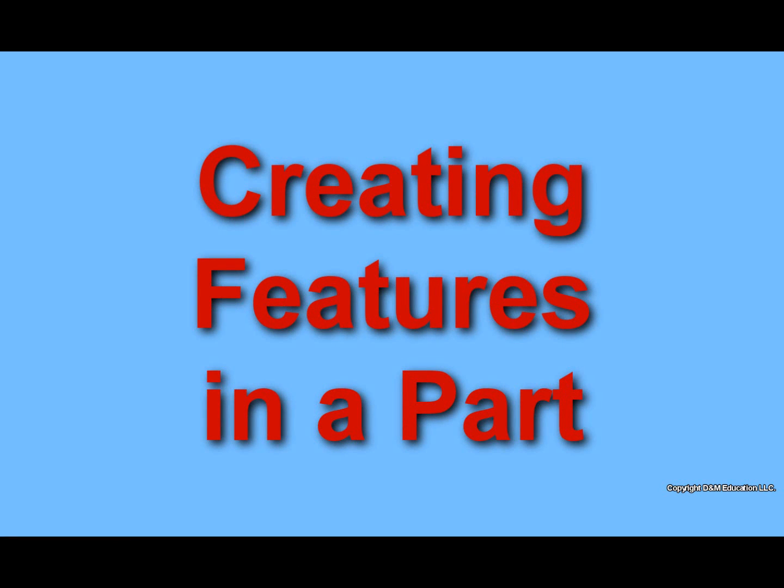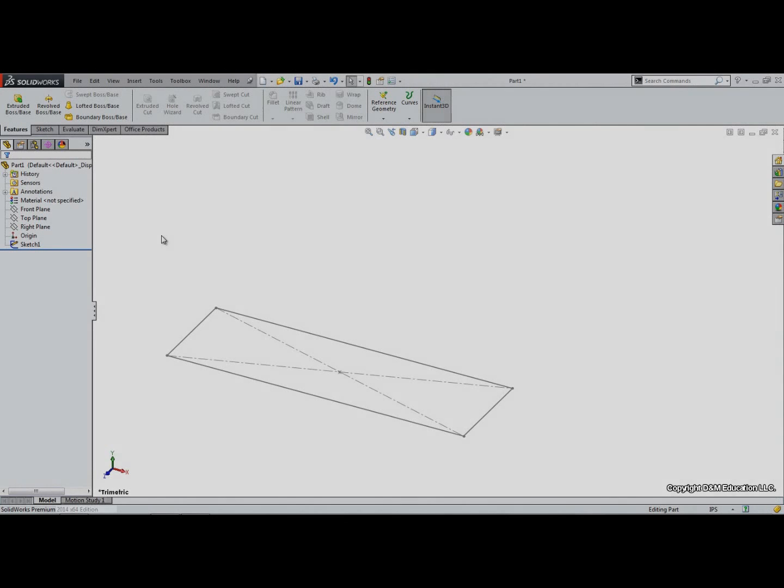In this video, the basics of creating features in a SOLIDWORKS part will be shown. In order to take a 2D sketch and turn it into a 3D model, a feature needs to be created. It is first necessary to have a sketch created before creating a feature. The commonly used features are found under the Features tab in the Command Manager.